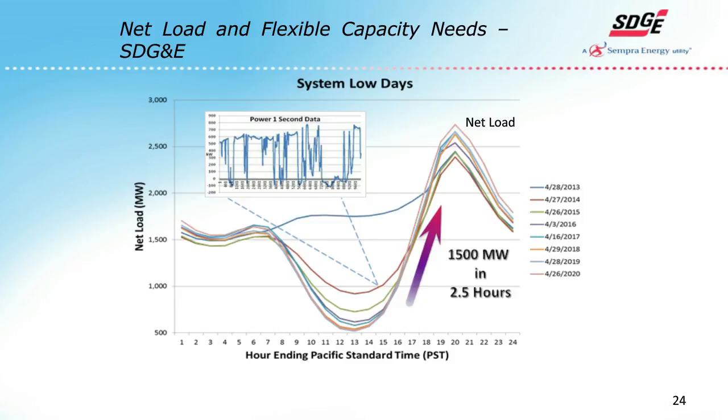But this data shows power production at a 1-second interval, and it shows highly intermittent power production. We're seeing that because of the marine layer impacts in California, in many cases no diversity with regards to some of the rooftop solar. So you can imagine a 680 megawatt power plant bouncing up and down, and the challenges that creates, not only with regards to a ramp, but also trying to smooth out and mitigate any transmission or distribution issues. And that's really some of the reasons why we'll talk briefly about smart inverters and why we've gone down the smart inverter road.